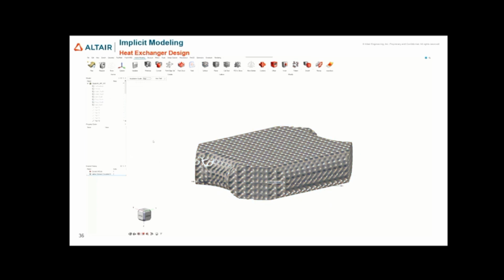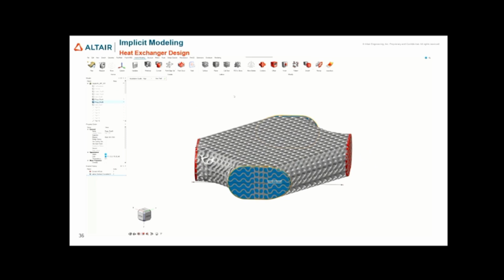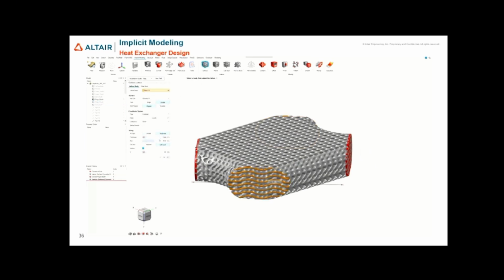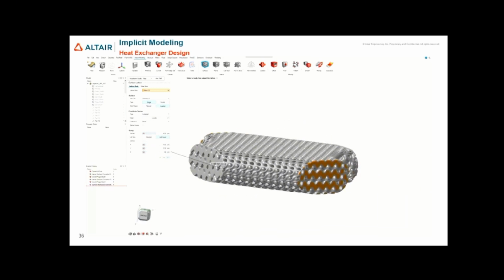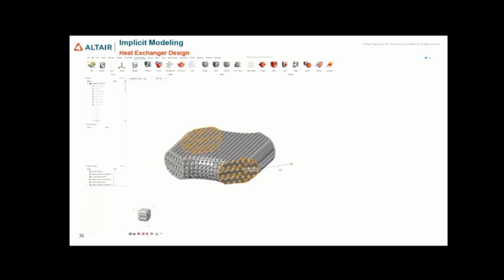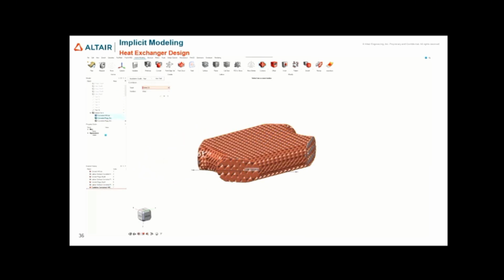And then we can make the plugs, so make sure that the fluid only enters in the correct domains. So we take those plug volumes that we designed, and then we just apply the same parameters that you had with your core, except in this case, you're not going to use the double lattice, you can use the single side, and then you can choose whether you want to keep or block one side or the other side. Do the same exact thing for the other plugs, except choosing the inverse side. And then all you have to do is Boolean those bodies together into a single body.